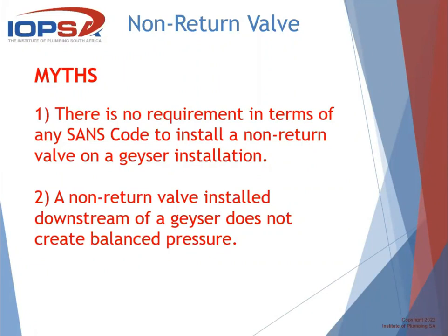But I think the other thing, going back to what you were talking about, is circulating the hot water distribution in a fairly sizable house. The biggest challenge is that the problems normally arise when it's finished. The key thing, and I've seen many of those, is to try and get that information before you start. As you're saying, Richard, you've got a pump that's running 24/7. The key is to go out and ask the questions, have a look at the flow rates, the distances, what's required, because it is sometimes very difficult to start rectifying these installations when we haven't asked the right questions in terms of the design.